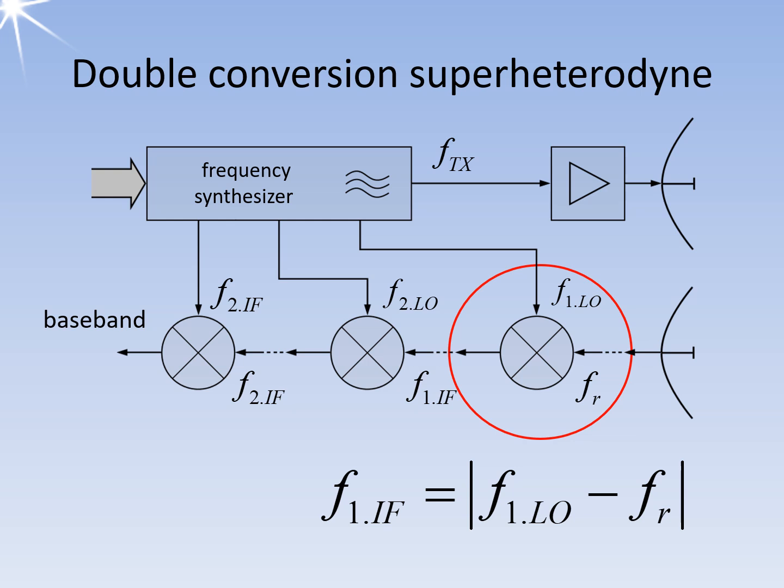In this case, a superheterodyne receiver with only a single down conversion can be used. A radar receiver operating in the S-band, which typically ranges from 2700 to 3200 MHz, requires a higher value. This requires two stages of down conversion.